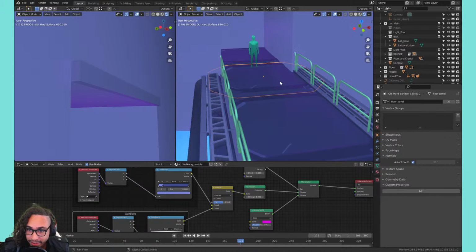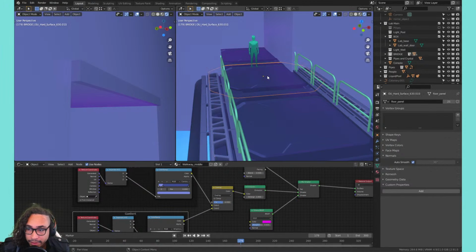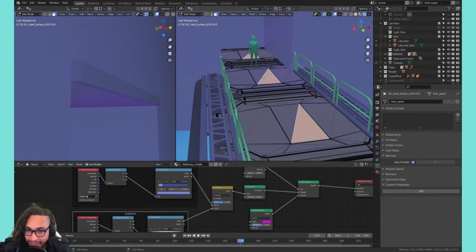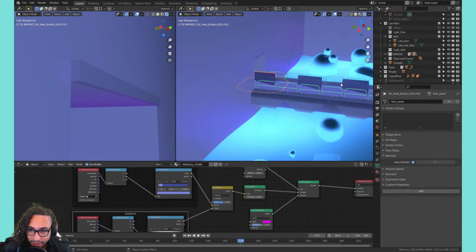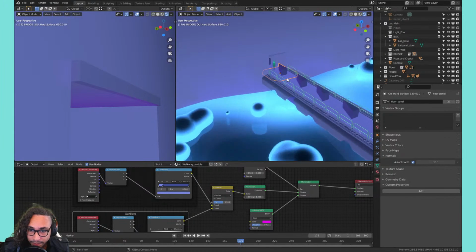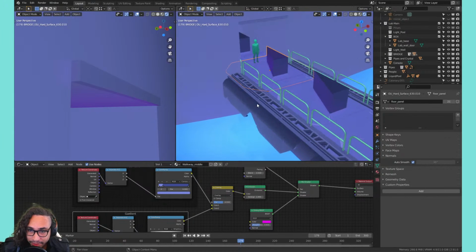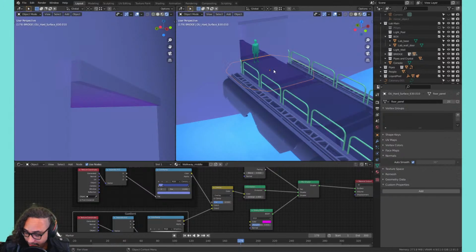And what that means is, hopefully I'm not repeating myself or it's annoying, but this floor panel is sharing the same mesh. So if I go into edit mode and I edit one of these, it edits all of them. So if I do some sort of edit like this, it gets the floor panel, and since these are all sharing the same mesh, that's what happens, right?